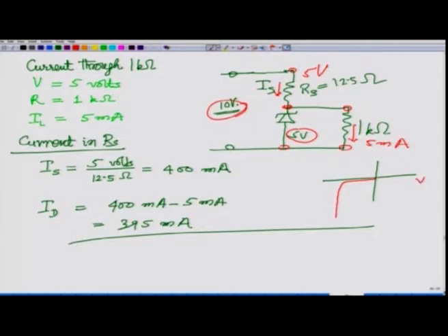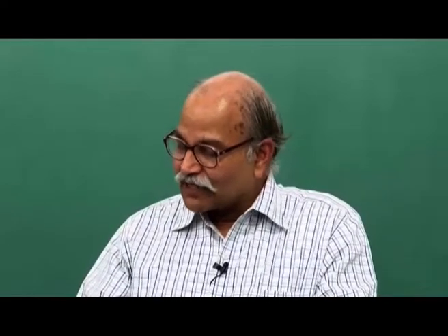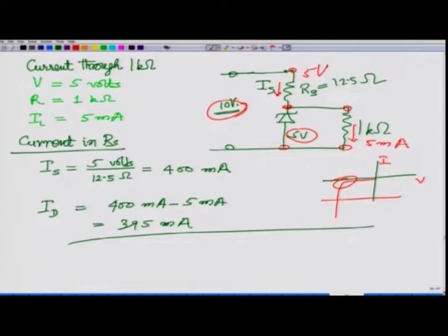So, you should not operate in this region, where it is still not a very constant voltage, the voltage is still changing with current. But if you are somewhere here in this region, the voltage is almost fixed, and therefore, there is a minimum current also, so that you are in that safe vertical region in this IV characteristics.